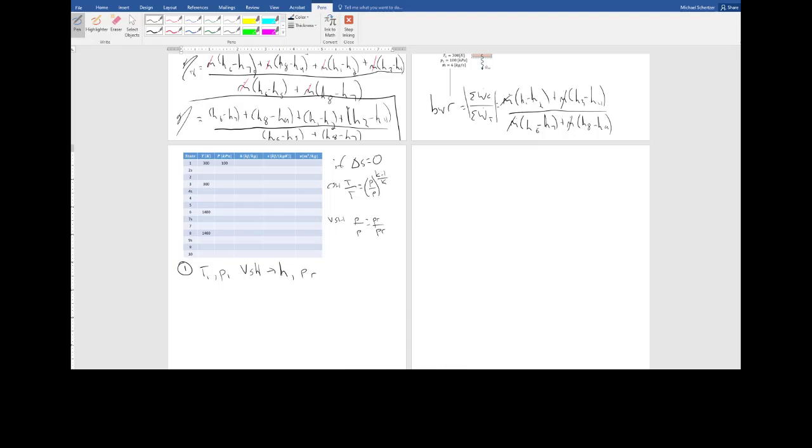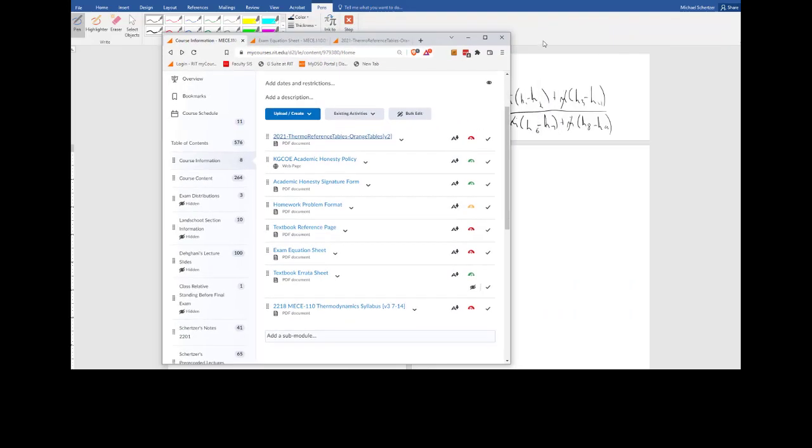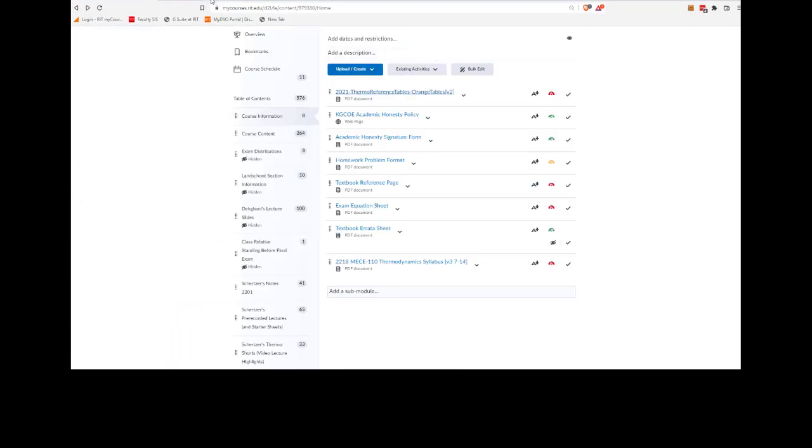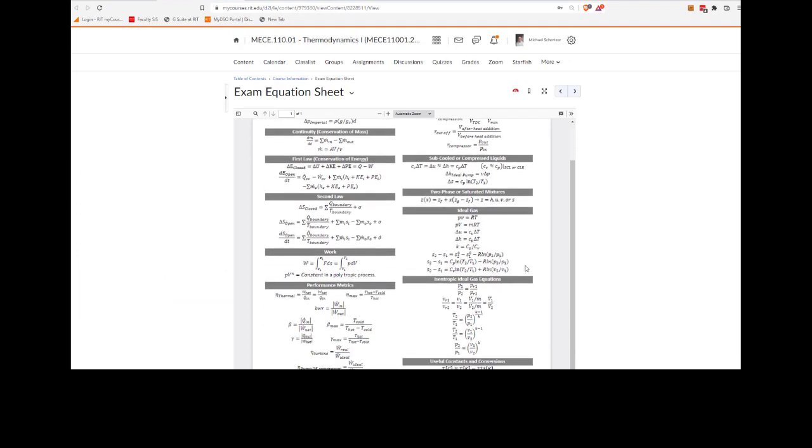If you want these equations, then you come over here and look at the equation sheet. For ideal gases, we're looking for isentropic ideal gases. We want K in the exponent if it's constant specific heat. We want a pressure ratio. We want PR over PR or VR over VR. But here, because it's an open system where we know the pressure ratios, then we're going to want this P over P is equal to PR over PR.